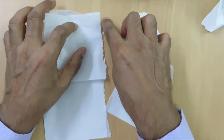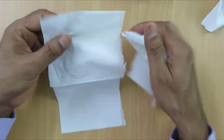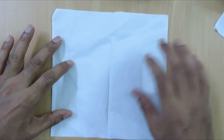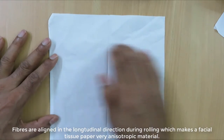Once the crack initiates, it goes through very easily because the fibers are aligned in this direction and I am pulling it in transverse direction. So through this experiment I have proven that a facial tissue which is made by a rolling process is very anisotropic. The fibers are aligned in this direction.